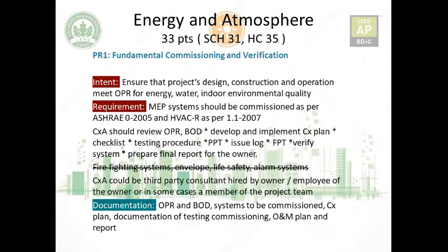So the whole concept is that you get the OPR and BOD, the design requirements, and you confirm that the systems are working as they should. If there was any problem, you have rectified that and you have moved forward, giving the operation and maintenance plan to the owner who hired you only for this purpose.